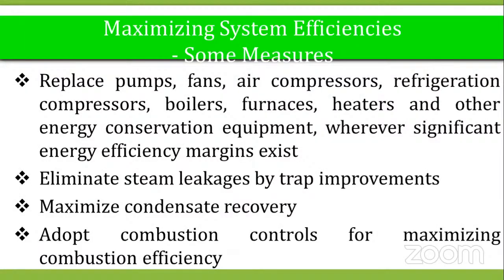So, maximizing system efficiency, some of the measures are: replace the pumps, fans, air compressors, refrigeration compressor, boiler, furnace, heaters, and other energy conservation equipment wherever a significant energy efficiency margin exists. Eliminate steam leakages by trap improvements, maximize condensate recovery, adopt combustion control for maximizing combustion efficiency.